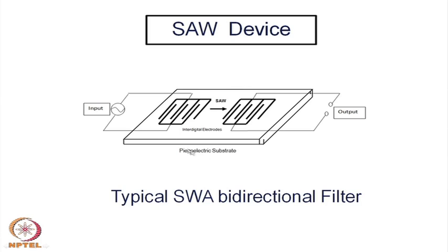And in presence of different environment, as I just mentioned, if there is a moisture or some gas, this acoustic waves gets changed, or their characteristics as well as the velocity as well as the phase difference gets changed, and therefore, one can detect the presence of such species, the environmental species like that. So, it needs a piezoelectric coupling to generate this kind of surface acoustic waves.